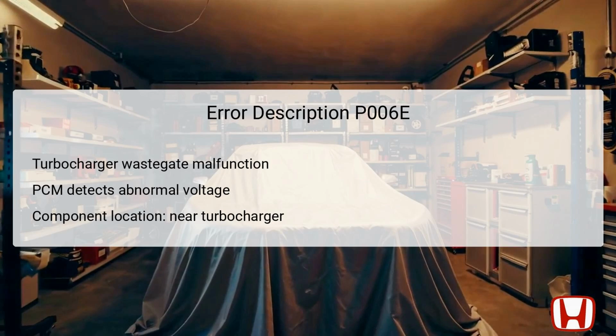The wastegate control actuator is crucial as it regulates boost pressure by controlling the flow of exhaust gases flowing through the turbine. The actuator is located near the turbocharger, integrated with the turbo system's plumbing components. A malfunction in this component can lead to suboptimal engine performance or increased emissions, making it critical for vehicle operation.